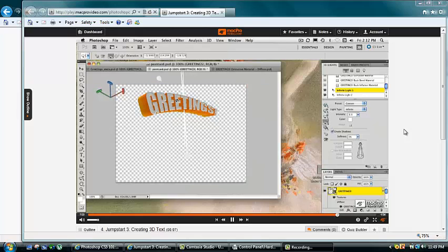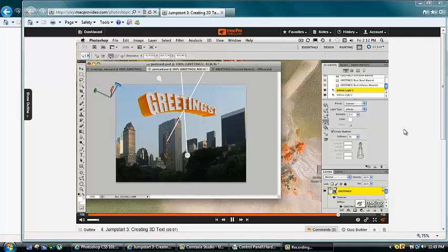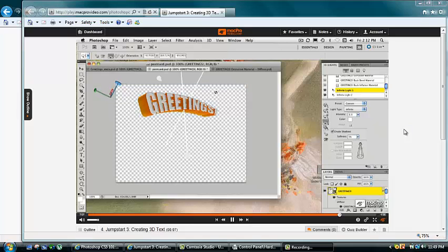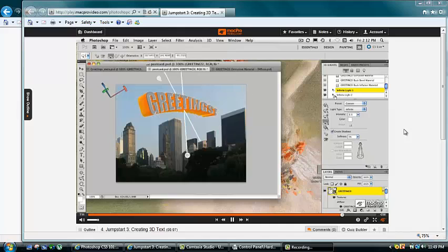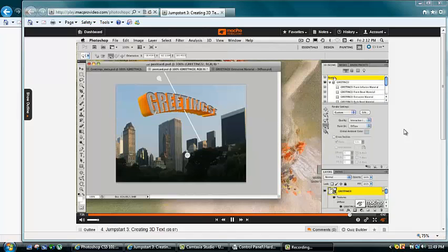So now as I move it around, you can see how this light trace, this line of where the light's falling, is changing the way it affects my mesh. So I'll go ahead and move my infinite light 1, and here's infinite light 2, which I'll turn off, and that gives me a nice shadow effect on there. So I'll go ahead now, that looks pretty good. If I go back up to my scene, I can then change to the ray trace look, and you can see it's just ray tracing this area in here. It builds it. It looks a lot better, very quick and easy.